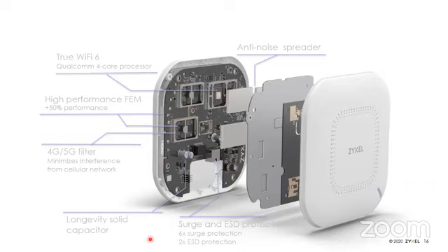But the other big cause of failure over time is heat fatigue, right? You've got these really warm chips in there, and you've got something stuck up on the ceiling. So what we do is, you can just barely see it here, but we've got a big metal plate that acts as a heat sink, pulling heat off the PCBA, and a number of vent holes across the back to make sure that heat exits there. So it keeps the heat down, where some of our competitors, not only do they not have a heat sink, they don't even have vent holes in their design. So they can advertise them as outdoor, sort of. And it does reduce the amount of time that the product's going to last before you start encountering failures.